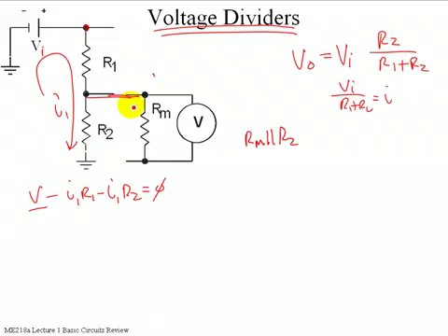Exactly. Whenever you have two resistances in parallel, if you think back to the hydraulic analogy, adding another resistance adds another flow path. That's going to cause a lower voltage drop to appear across that because you've lowered the overall resistance to flow. The same is true whenever you put two resistors in parallel: the combined resistance will be less than the smaller of those two resistors that you put in parallel.